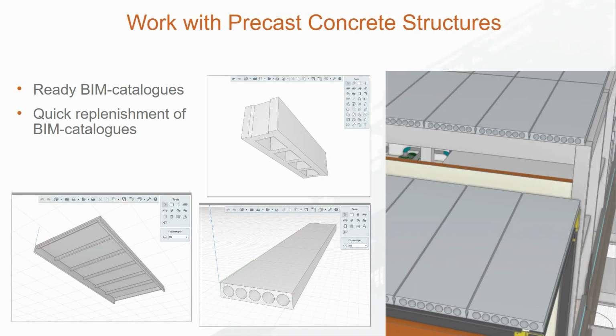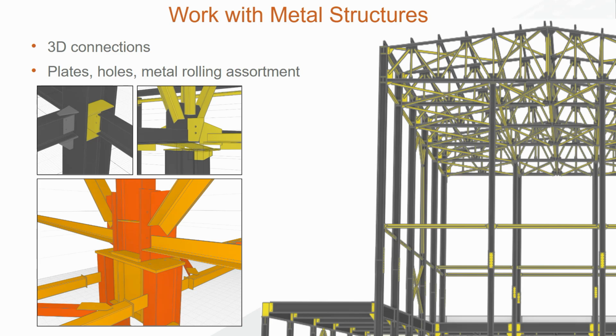Another Renga option is to work with precast concrete structures. The profile editor can create profiles of any type and shape for precast concrete structures. Renga provides tools for detailed 3D connection design and creating metal rolling assortments, plates and holes of any type and shape for those who design metal structures. Let's take a look at how users work with metal structures.